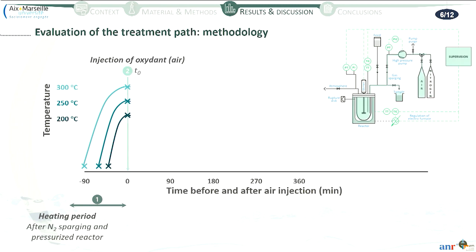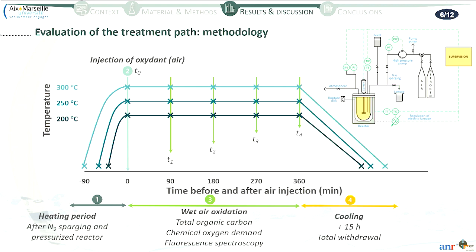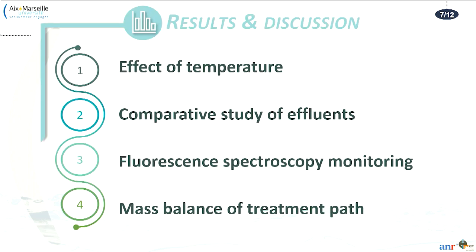When the temperature is reached, we inject the oxygen. In our case, it was air. And then the oxidation starts. We performed an oxidation with a long duration, 6 hours, and we withdrew several samples every 90 minutes to characterize the organic fraction through total organic carbon, chemical oxygen demand, and fluorescence spectroscopy. At the end of the reaction, we cooled the reactor, and we did a total withdrawal of the reactor.